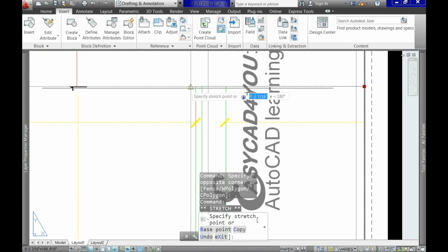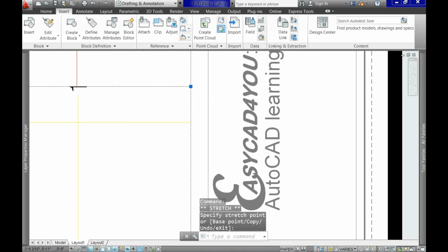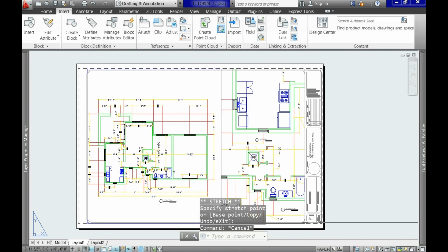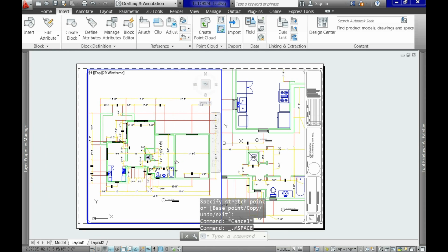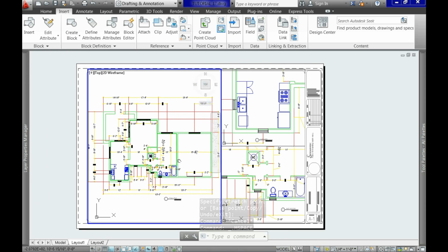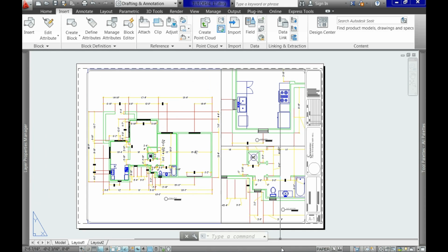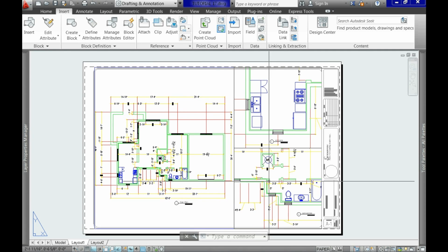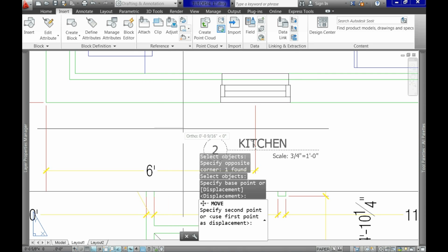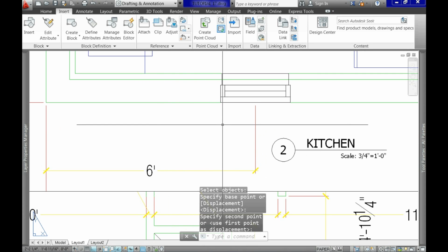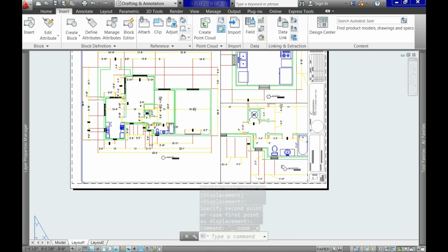Just have in mind that this was the subject of the previous tutorial. Now, to toggle between paper and model space, we use the button at the status bar. On the other hand, to adjust the drawing within the viewport, most likely you will have to pan a little bit. Now, repeating what we were doing, we have to change the paper space again to move or adjust the objects that are in paper instead of in model space. Like, for example, here, this title for the second drawing.